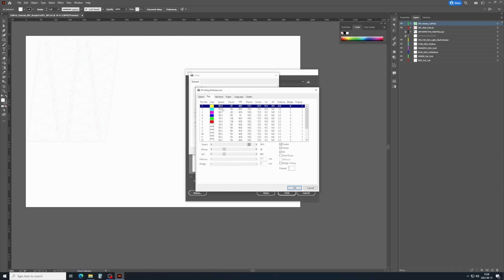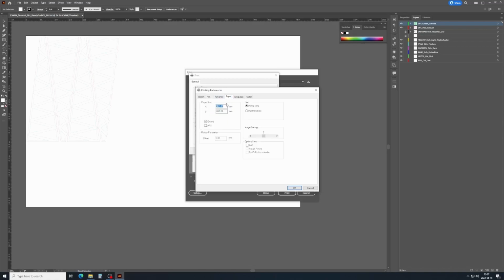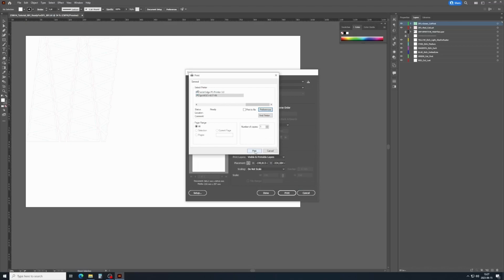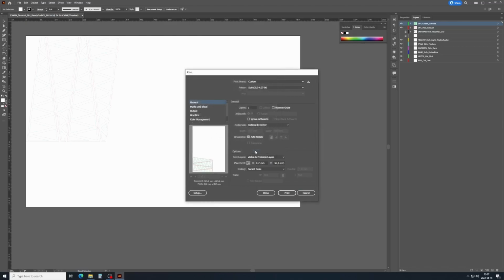You may modify the values as you see fit with regards to the material that you have chosen, but for an initial test run, the defaults might as well be used. Click OK to confirm the laser cutter printer driver settings. Click Print to confirm. Select the Laser Illustrator media size preset and make sure that the placement is at the top left reference corner. To save these settings without sending the operation to the laser cutter, click Done.